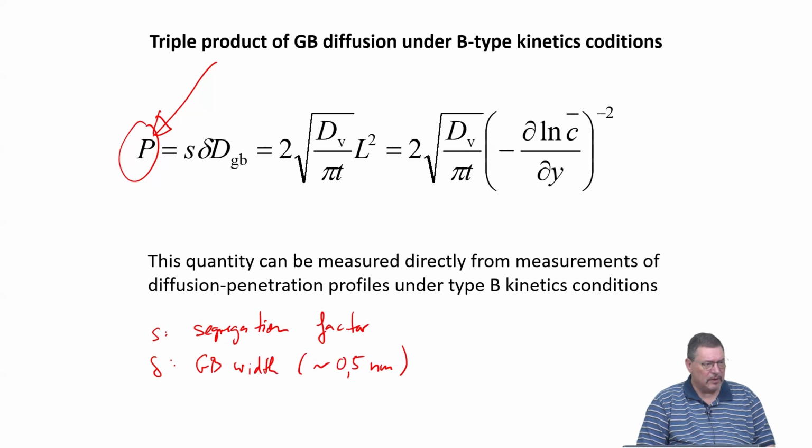So we have to take into account, when we do measurements at specific temperatures, in which regime we are. And for certain materials, we need to know: is there segregation occurring in a measurable, strong way at the grain boundaries, or is there no segregation, or a value very close to unity?